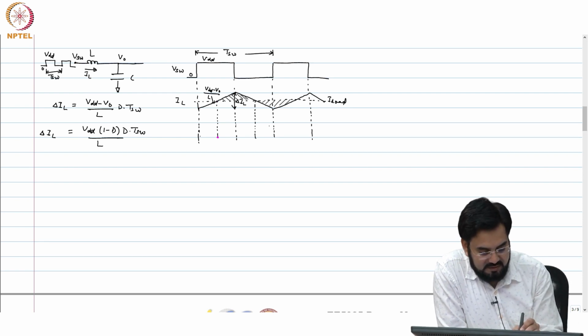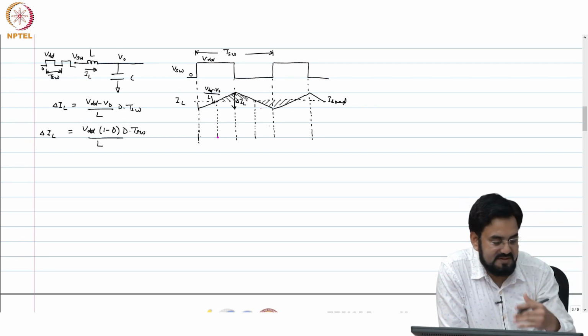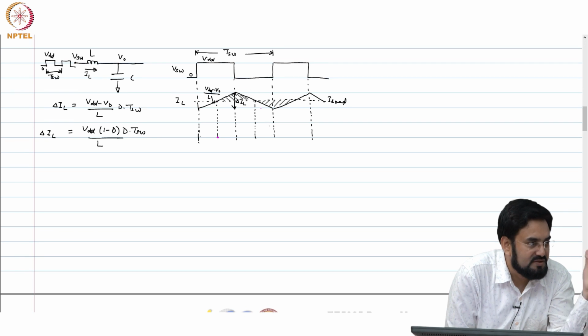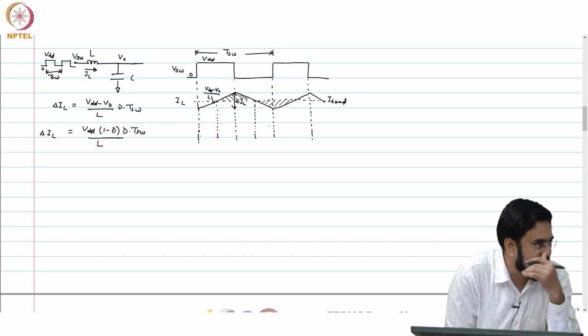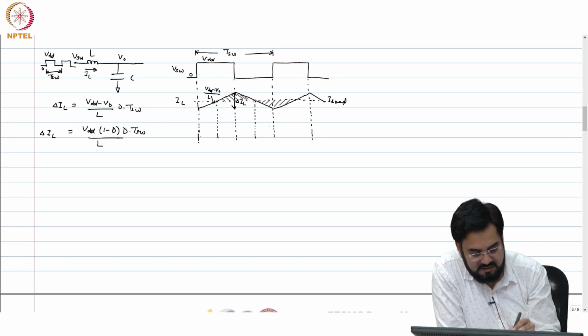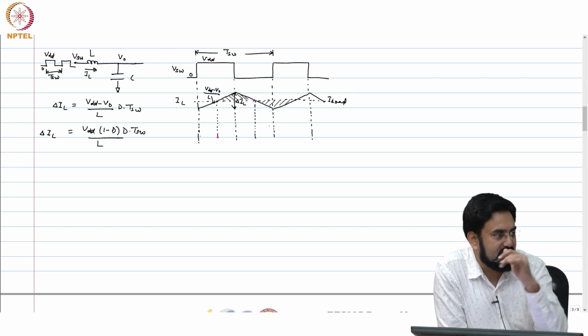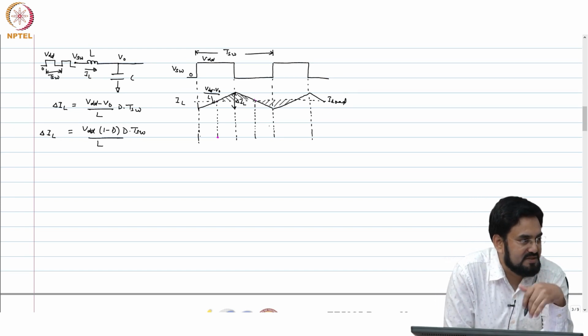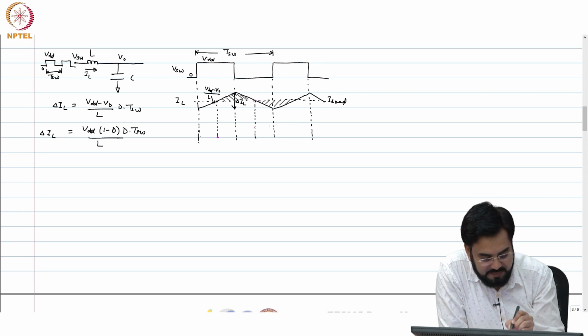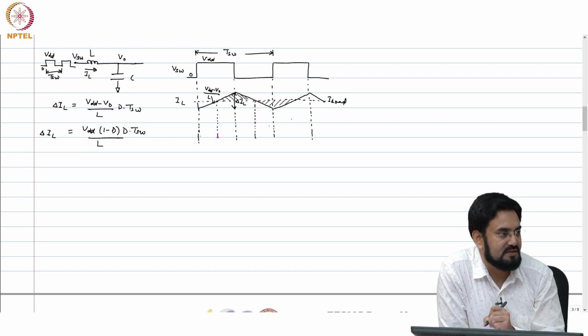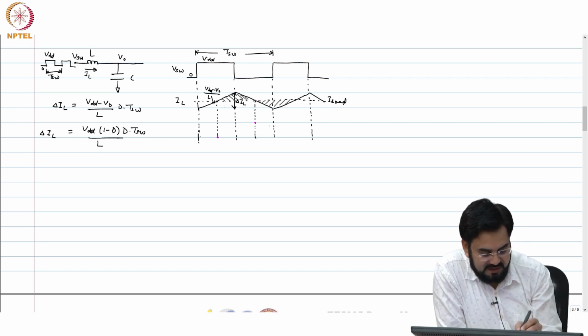And so, if you look at this shaded curve, which is above your I load, average current is positive. So, it will keep charging, the capacitor will keep charging until this point, where again your current becomes negative and the capacitor will start discharging, which means your peak will be reaching here, and then again it will start discharging. Okay. So, even if you integrate it, your shape will look like this, correct.